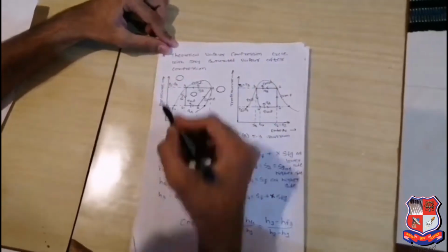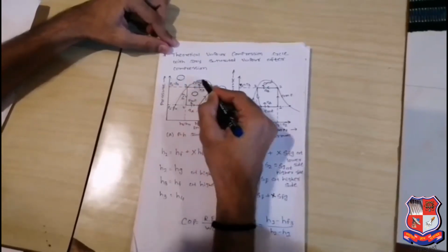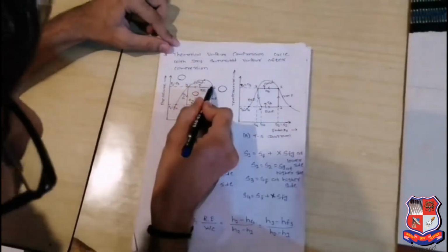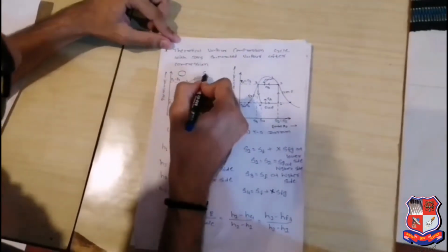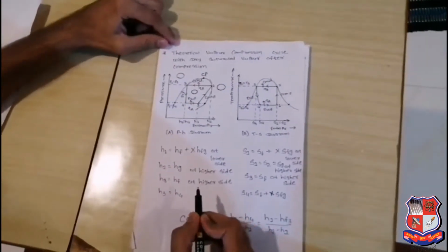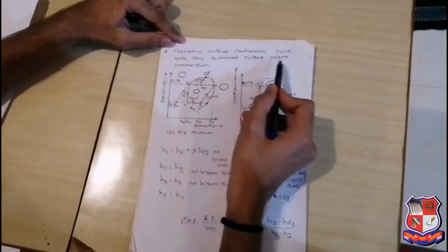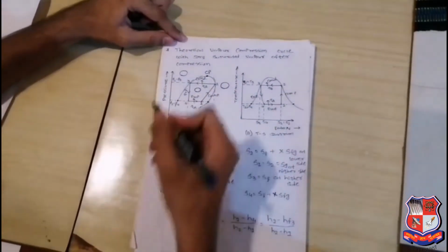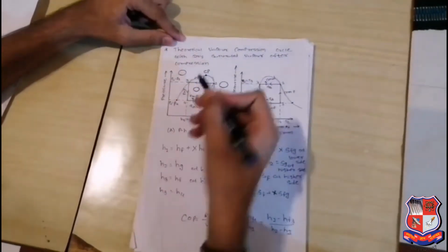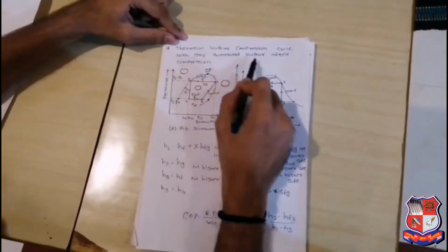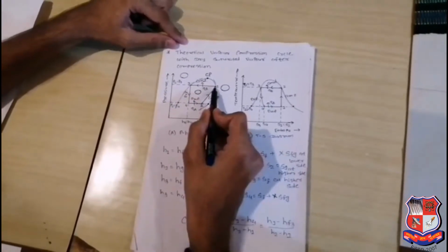Now we are going to discuss about that curve. That curve will be considered that is your saturated liquid line. That line is called as a saturated vapor line, and both are merged at one point. That point is called as a critical point. Now according to our theory, one case is given, dry saturated vapor after the compression. So we can say that in VCR cycle 1 to 2 is compression process. After the compression, that case will be given dry saturated vapor. It means second point is directly given on saturation curve, dry saturated vapor.